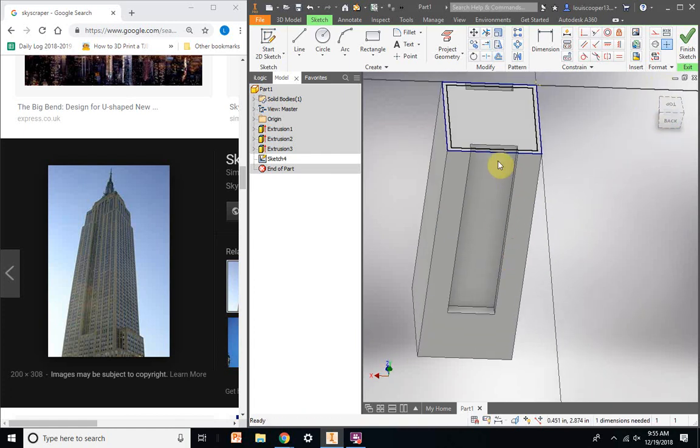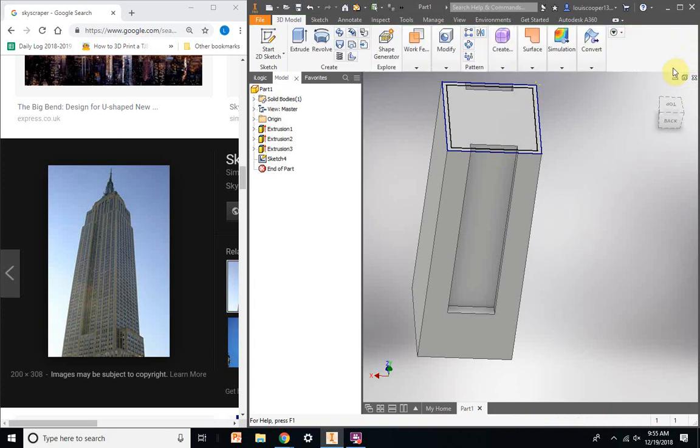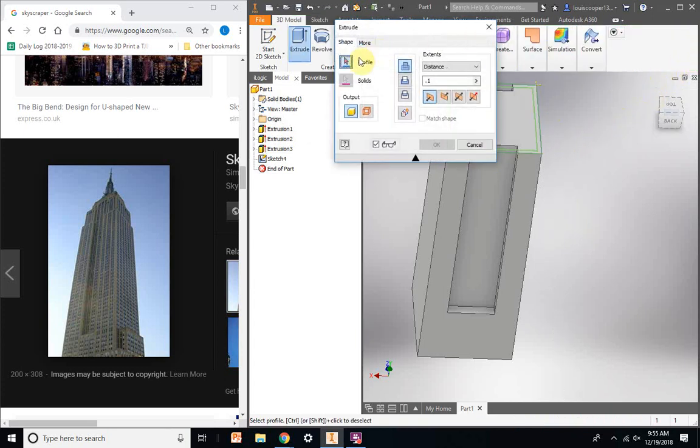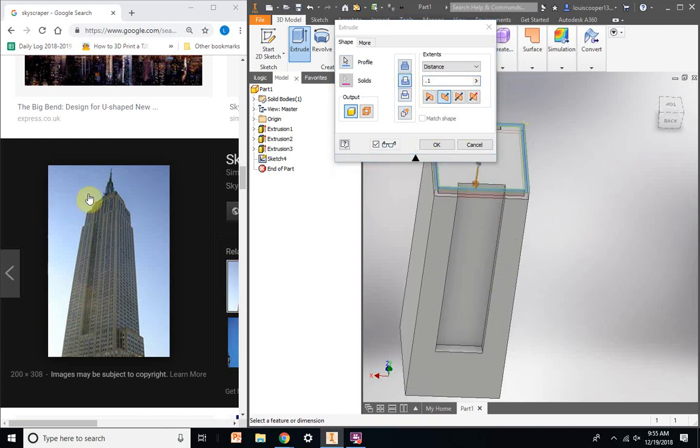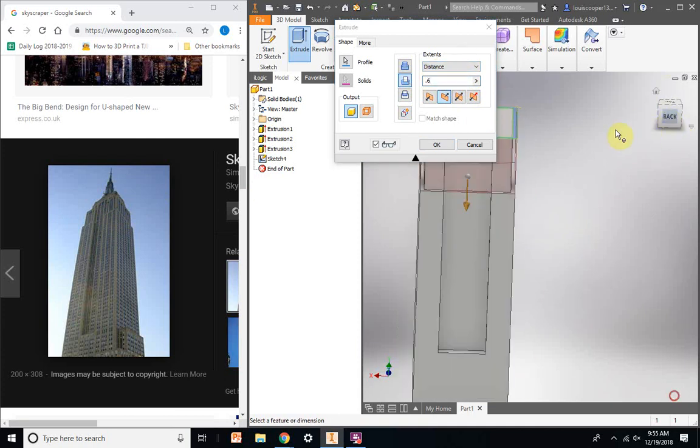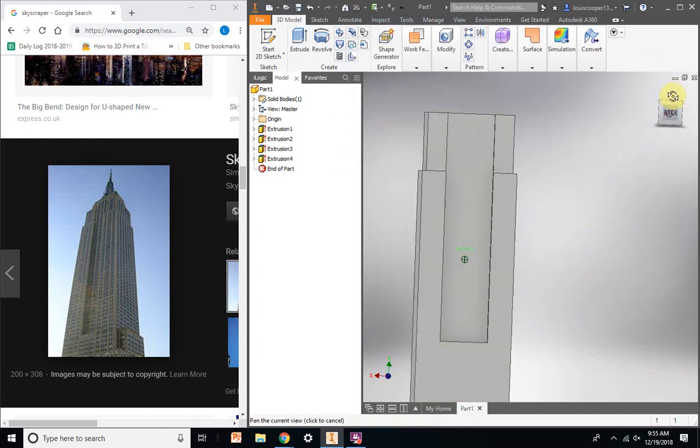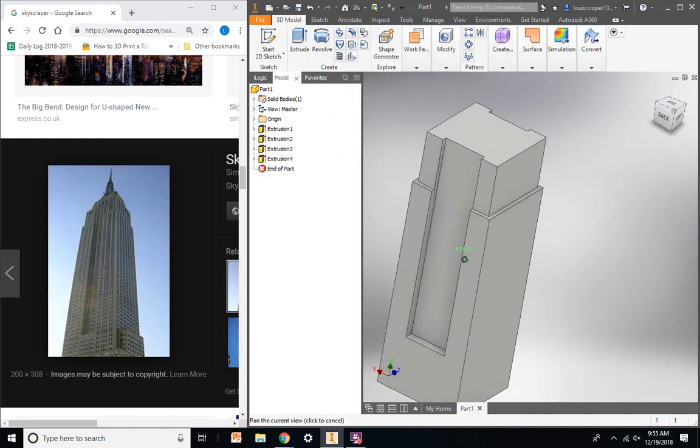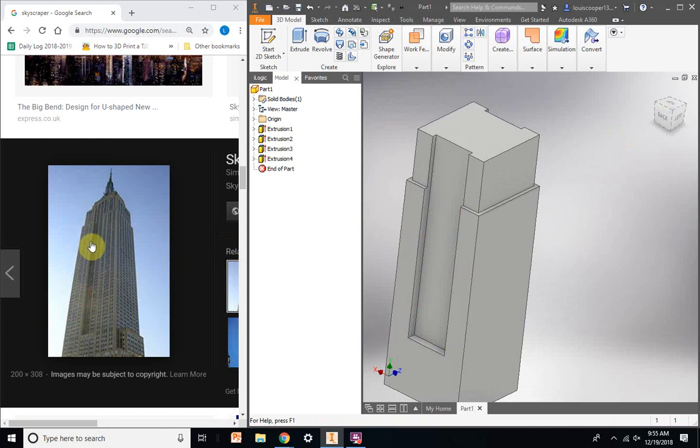And I know I'm going to bring it probably like this, okay? Because I'm going to cut, and I'm going to show you, if I finish the sketch, I'm going to cut with extrude, and I'm going to click in here, extrude, cut it, and I'm going to do the very top part, so I'm going to do about, I don't know, 0.6. Looks pretty good, so I hit OK. Okay, so now, let's take a look at that compared to this. It's getting there, okay, so I have my indent and the cut-in. It's not exactly the same, and that's okay. So that's there, okay? And then I would continue to do this process.